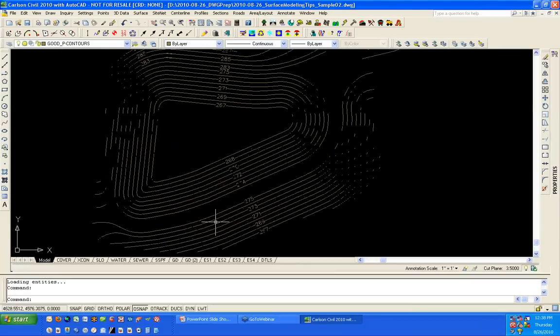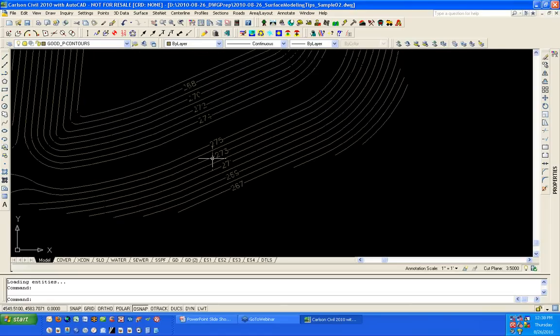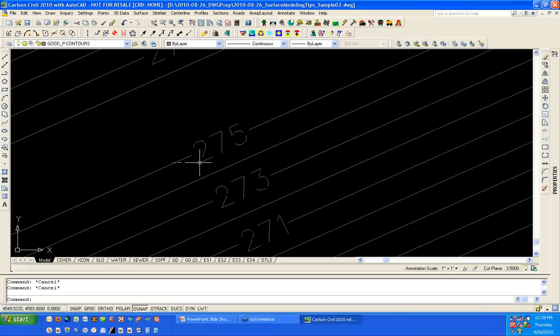Now what's our next step? We still have lines, we have polylines. I'm going to use another Carlson command to elevate some of these contours, maybe one you haven't used before. And if you look at all of the different pieces, order of operations matters. Doesn't it make sense that I would want to connect across this first for all of these? So first step would be to connect these. I'm not going to do all of them, I'm just going to do a couple.